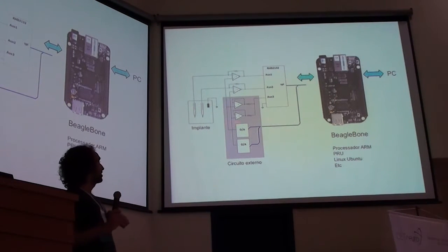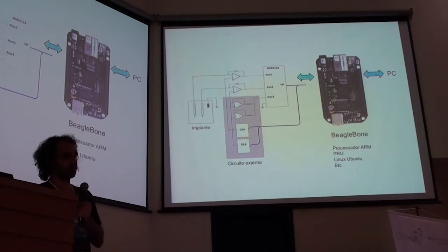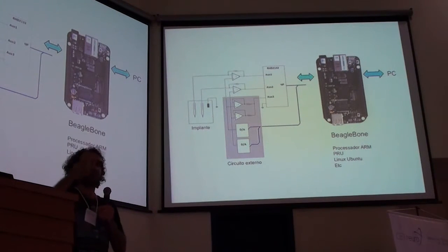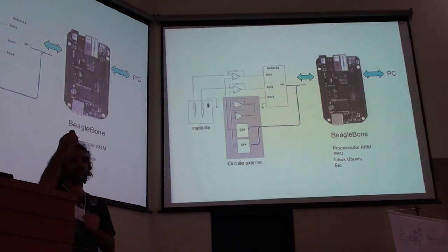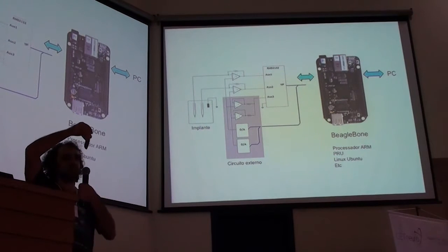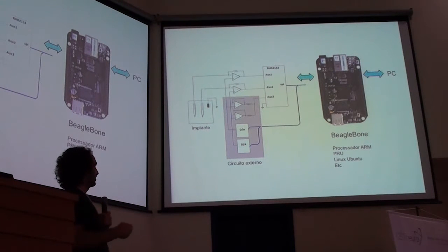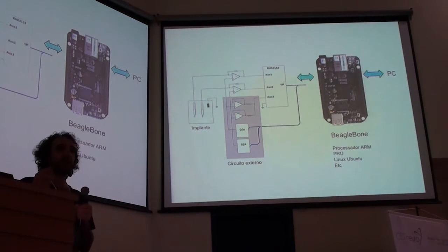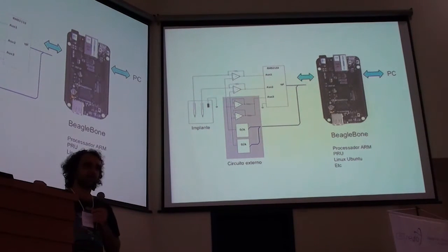And also because it has wireless, we simplified the connection even more. Instead of having a rotary joint and so on, we have the BeagleBone with a battery and a rigid cable that connects the head stage to the BeagleBone, and we just tie the BeagleBone with a nylon string. So when the animal spins, the BeagleBone spins together. Then you don't need a commutator joint, and you avoid mechanical artifacts and so on. And the data is transmitted using normal Wi-Fi. So we can get like 32 channels, and yeah.